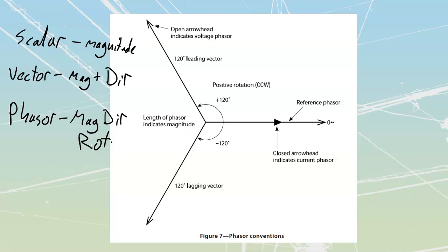Because it's a three-phase system, we're actually going to have rotation. It's as if the peak of A, B, and C goes from one to the next as we go all the way through, which means we are going to have continuously moving voltage. That would be an absolute pain to analyze. So what we are going to do is take our phasors, these magnitude directions that have rotation, and go one at a time. We're just going to lock them down and take snapshots in time, and that way we can look at all of this stuff. So understand that it's always rotating, but we're only looking at it as if it were small snapshots.